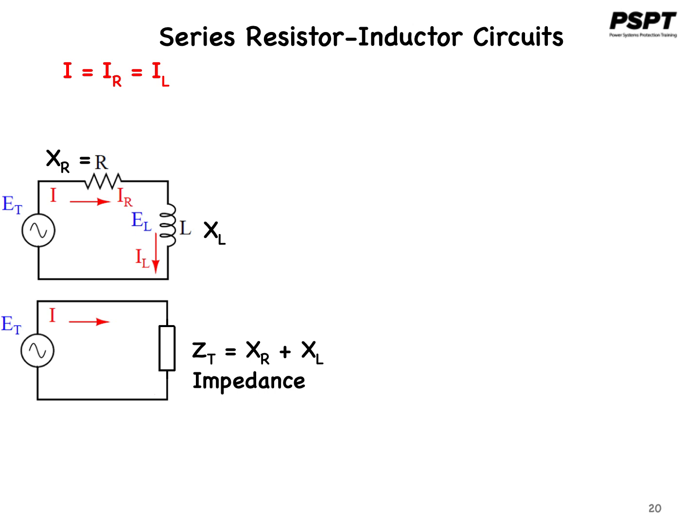We just learned from the previous slides that the voltage drop across the resistor is in phase with the current in the circuit, and that the voltage drop across the inductor is 90 degrees out of phase with the current. In other words, the inductor voltage leads the current by 90 degrees, giving us this orientation of phasors of the current and voltage in the circuit.